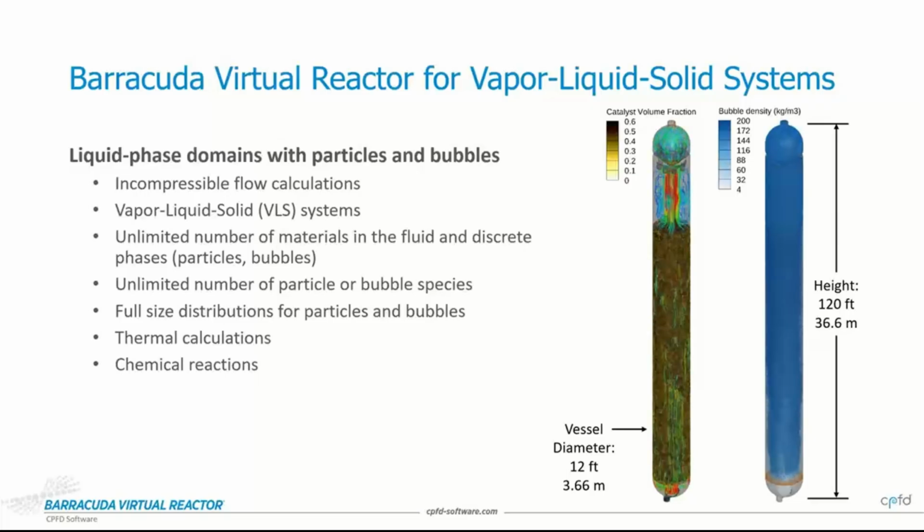So the fluid acts on the particles with drag, the particles displace the fluid, and again, it's fully tightly coupled chemistry and heat transfer. The particles and bubbles are discrete Lagrangian entities. The fluid is an Eulerian phase, and they are both resolved independently against the grid. And as I said before, they are coupled, so they affect each other across each time step.